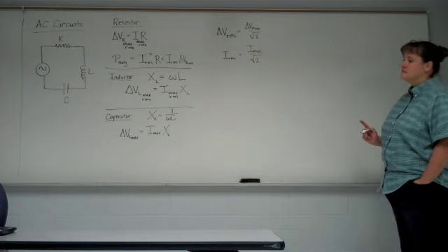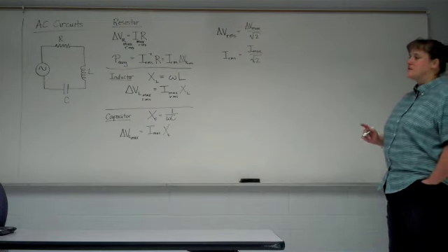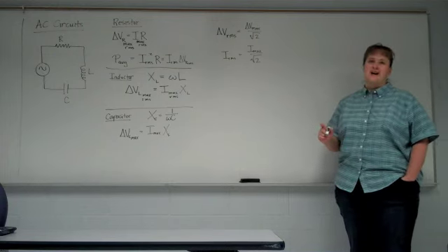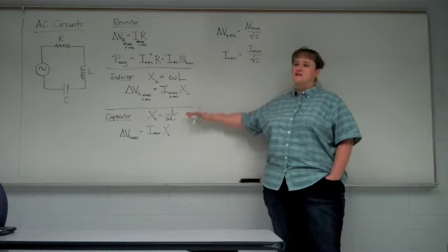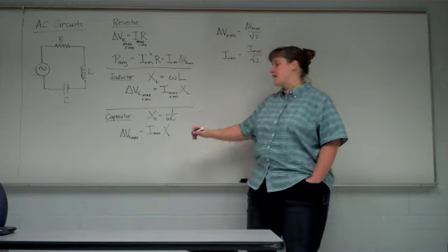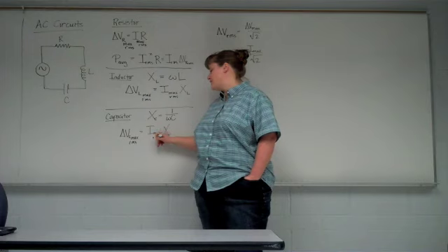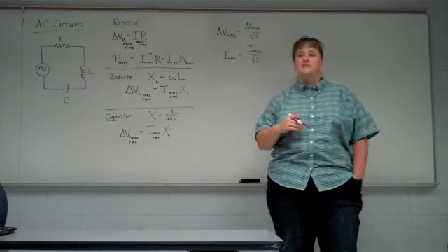Now, please keep in mind, for both inductors and capacitors, the maximum value of the voltage and the maximum value of the current do not happen at the same time. These are not time-dependent equations. These relate the maximum values and they'll relate the RMS values, but they will not tell you the value of the voltage at any point in time.